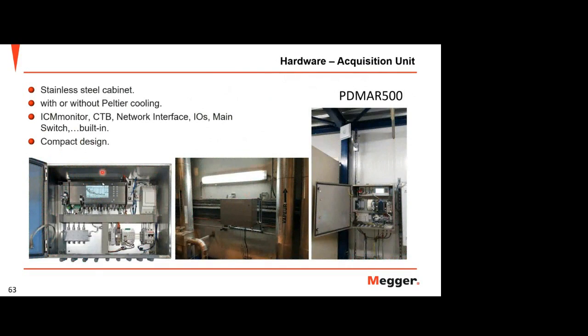We supply a special panel, a stainless steel cabinet with or without Peltier cooling, complete with the temperature sensor, CTB, and preamplifier, all inside this panel, IP65. So this is a good option to install to monitor your PD on your online rotating machine.